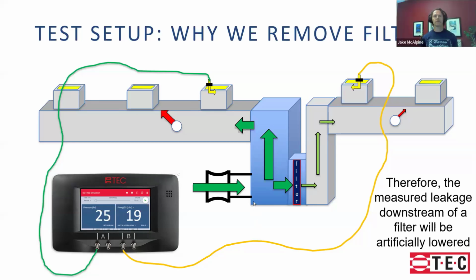Yeah, we're using a test pressure. We're all agreeing to test at 25 pascals. We're looking for uniformity in how people test the systems so that we can compare, and so that we have decent results that are portable, that we can take between houses, between systems. Okay, thanks very, very much.